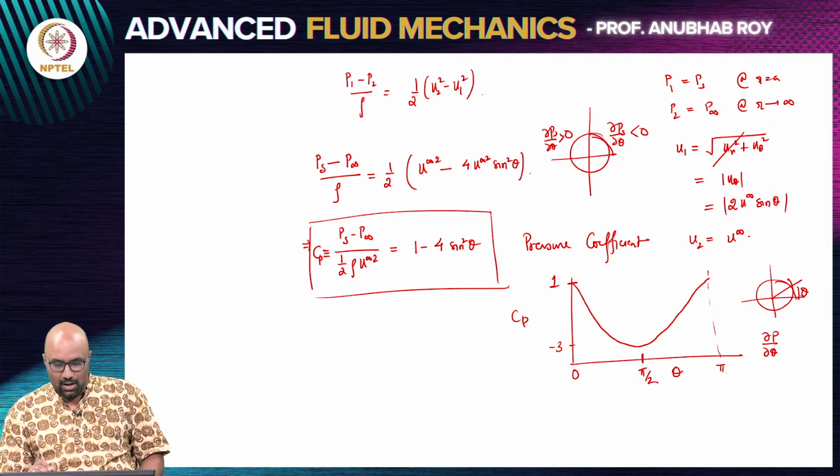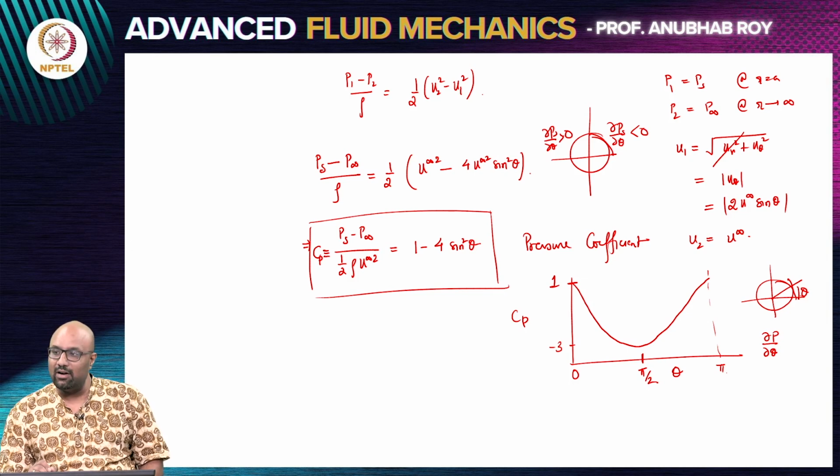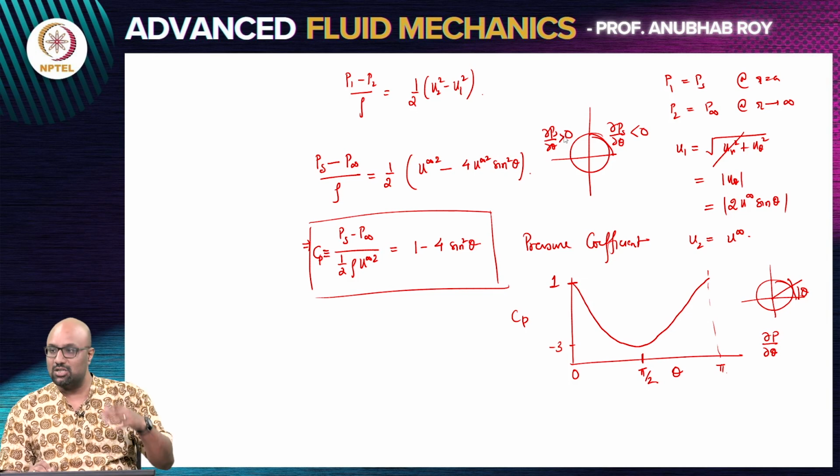Okay. So, this is where we have pressure calculation. As you saw, it got significantly simplified. Nowhere did we explicitly solve Euler's equation. We saw Laplace equation, which had nothing to do with momentum conservation. It was basically based on two constraints, incompressibility and irrotationality, with the boundary condition of no penetration. So, we use these constraints and the boundary condition to get the solution of velocity potential, and then we use Bernoulli, which was obtained from Euler, in order to obtain pressure.